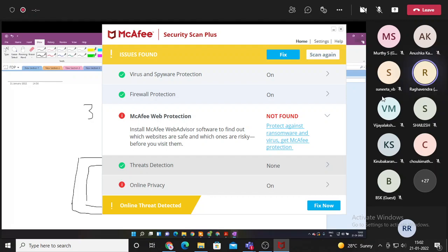And understand one more thing. This particular daughter board does not follow IQ, meaning there is no addition. You don't take I and Q components. You only take the I and you give it over here. You take the Q and you give it to another port. You have a second port with a second set of local oscillator. Right now, we've done it using a 2920 motherboard, so you only have one I and Q, and each of them goes to a particular port.